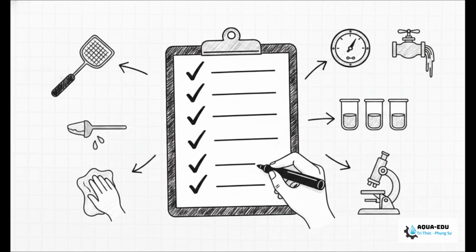Measure the oil, verify the air, run the jar test, check the microscope, skim the foam, clean the DO sensor, trace the logs, evaluate the oil type, increase the wasting, log the incident. Ensuring that not a single critical step is missed is exactly how we save the plant.